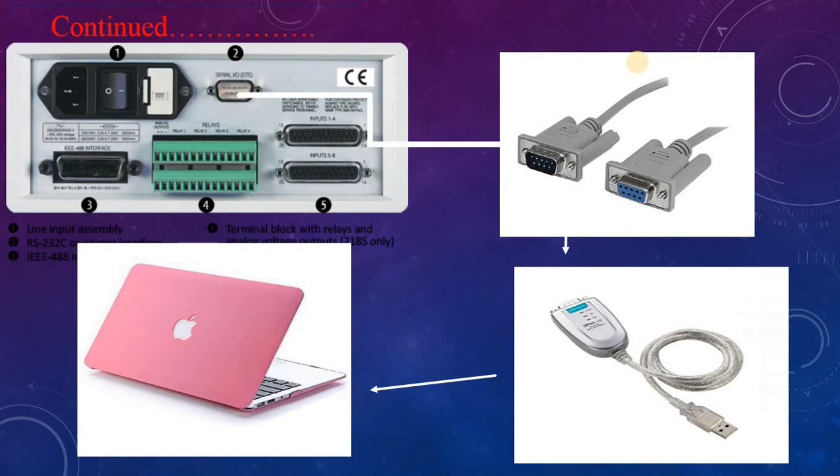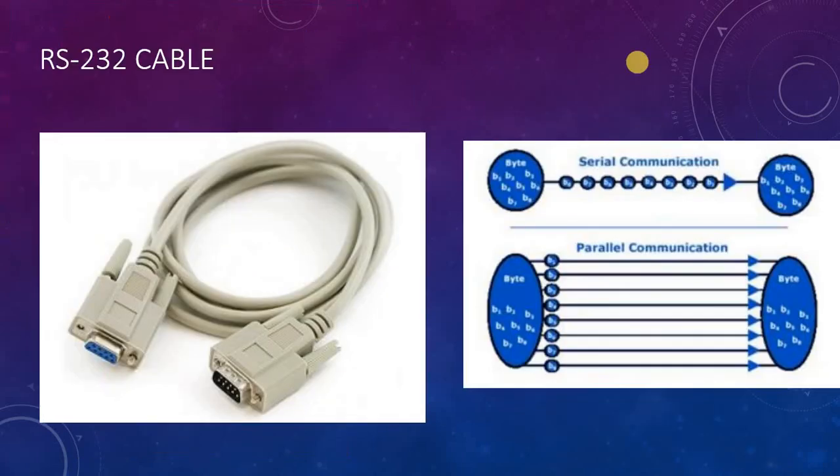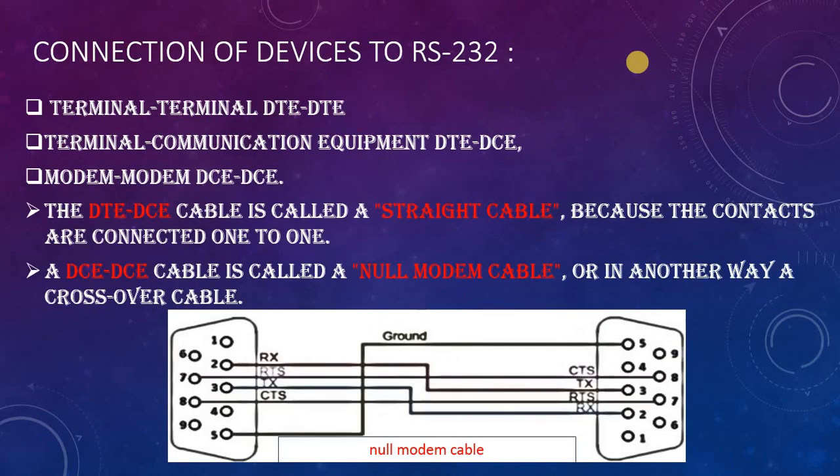You can see on the screen the last one, this 9 to 9 pin null modem cable, is made like this. In fact you don't need all these 5 wires, but you probably need 2, 3 and 5 on the left hand side, and on the right hand side also 2, 3 and 5. Usually only these 3 wires are required.